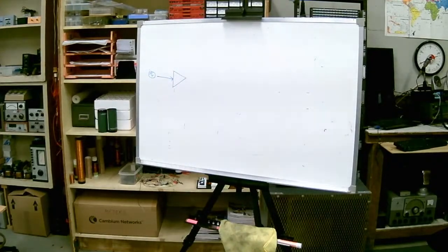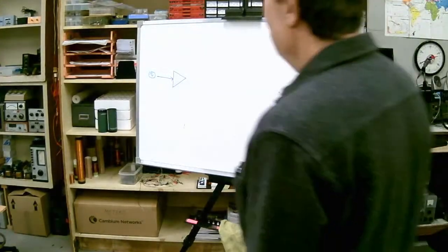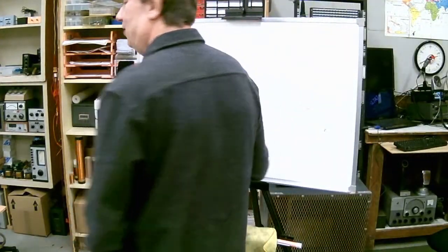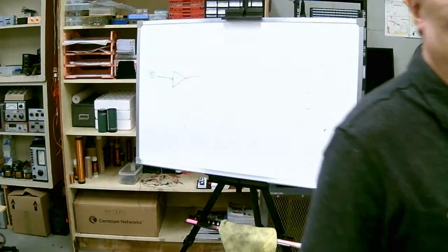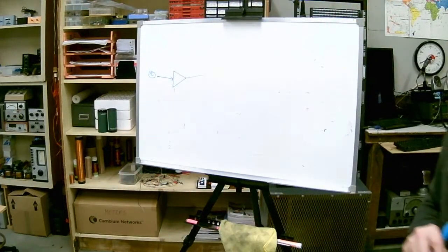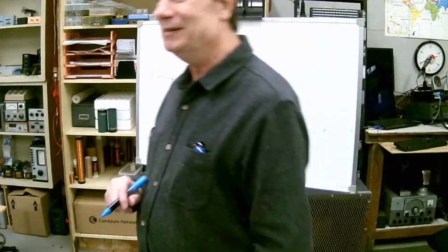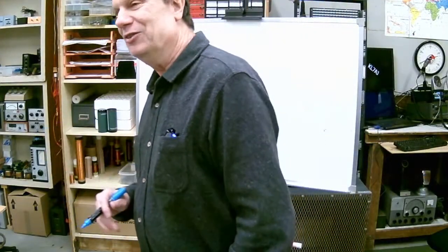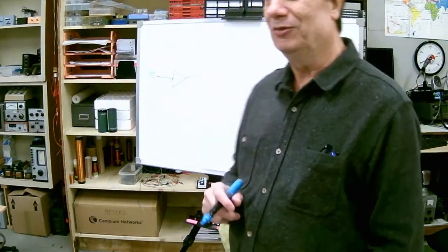You want to be able to tune into a certain frequency. Okay, very good, that's one function there. And then detect a signal on that frequency, and then you want to amplify that so that you can know what that signal is. One of the important things, probably more important than amplification, is selectivity. Pick a frequency, right? Otherwise, you just have an amplifier, and it's going to amplify everything out there. Most of the time, we don't want to hear every radio station at once, so we need some means of selectivity.